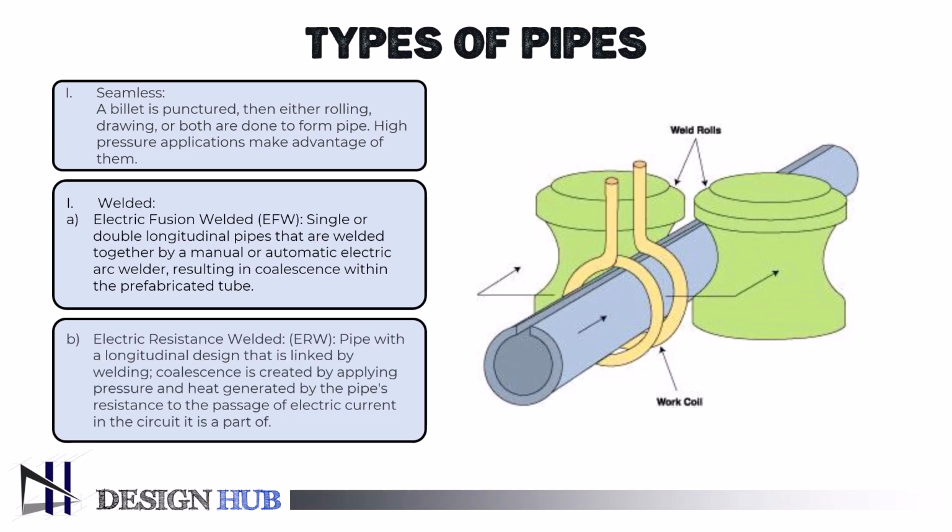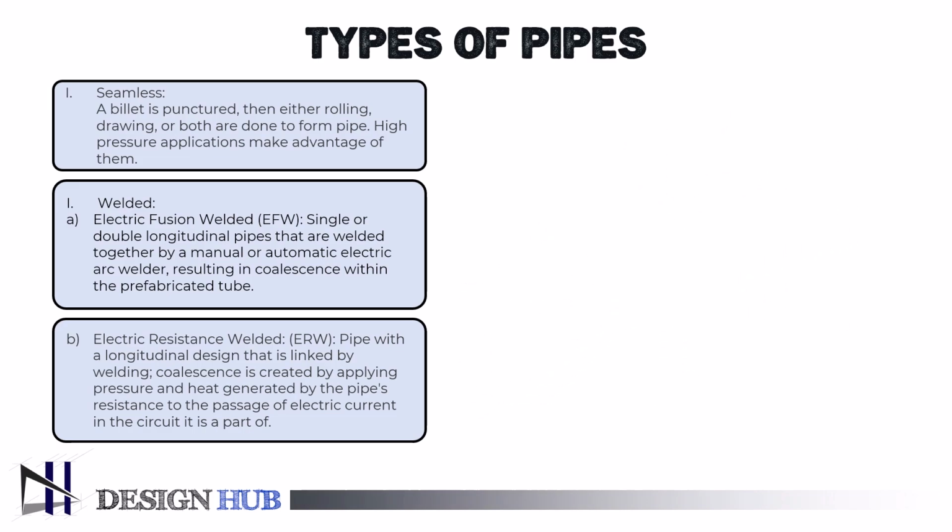Steel sheets are cold formed into cylinders to create electric resistance welded, ERW, pipe. The steel is then heated to a point where the edges are pressed together to form a bond without the need for welding filler material, by passing current between the two edges of the steel.